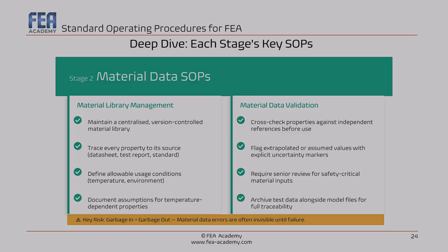It is a centralized version-controlled material library with 4 mandatory fields for every entry: the property value, the source document (a datasheet revision, test report number, or applicable standard), the validated temperature range, and the date and the author of the last review. Access to add new entries is restricted to a nominated data person. It's very important. It's not an open database. All users can read, but not all users can write.